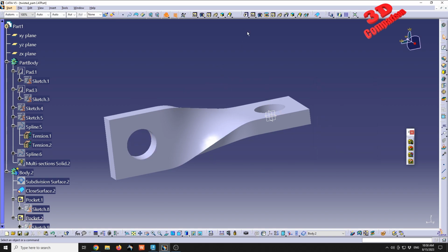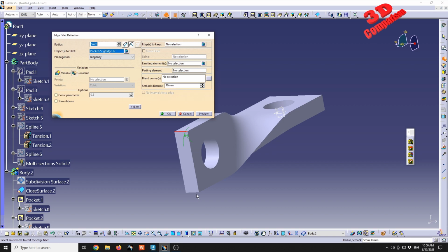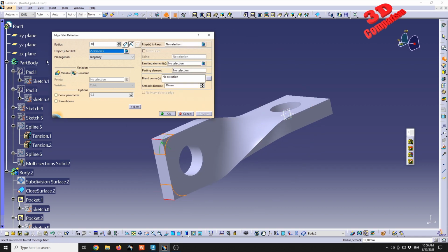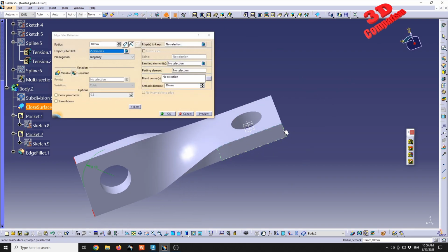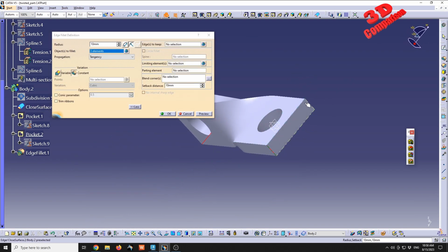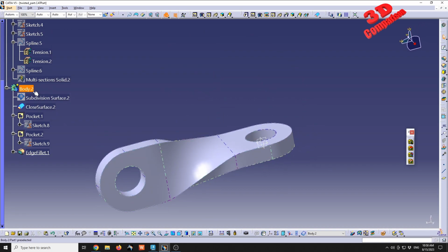And we still have those fillets for the sides. So if I go with a fillet of 5, this should do like that. So a fillet of 10, this should do that full half circle. And we can just define the same fillet for the other edges without having the need to create an additional one.